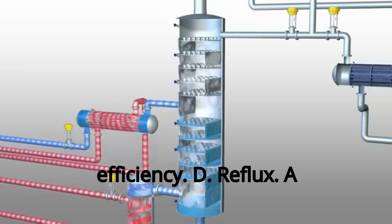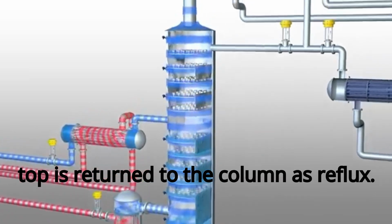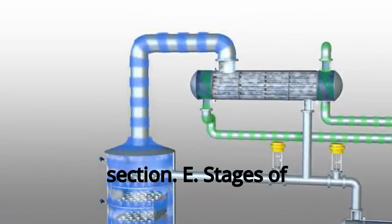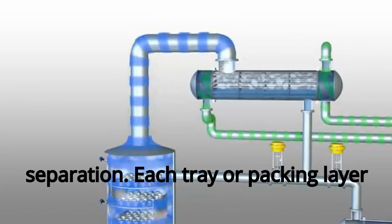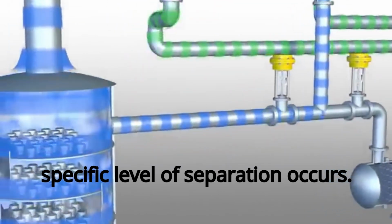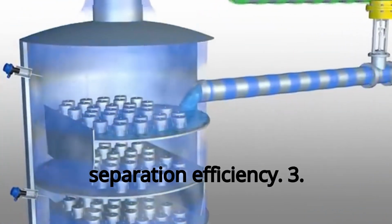D. Reflux. A portion of the condensed liquid from the top is returned to the column as reflux. Reflux improves separation by enriching the lighter component in the rectifying section. E. Stages of separation. Each tray or packing layer represents a theoretical stage where a specific level of separation occurs. More stages or trays result in higher separation efficiency.